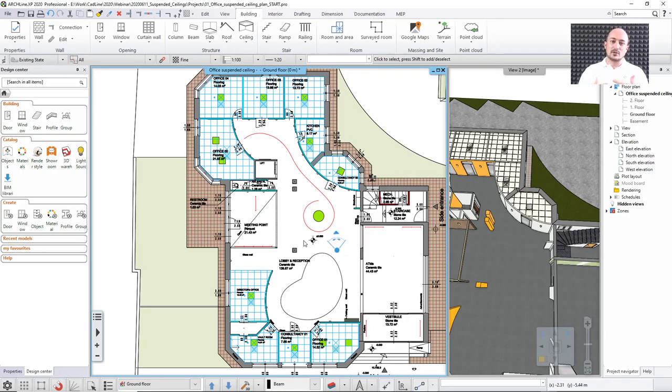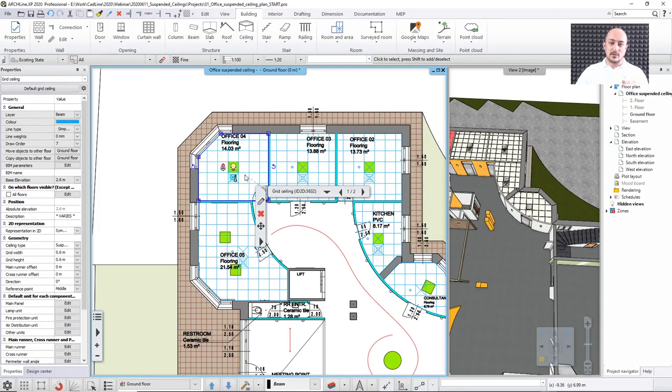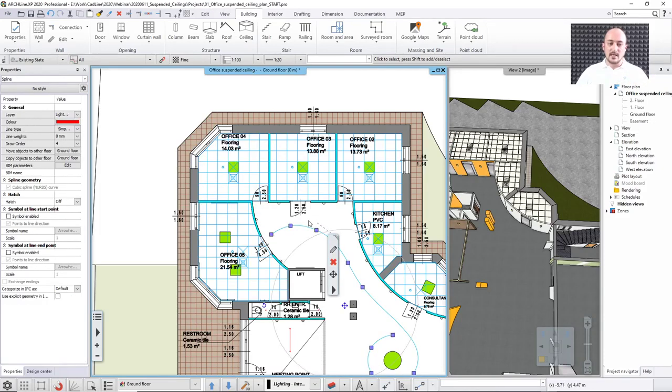So it is faster to generalize it, to create these items automatically and then customize them, than to start each and every time over and over again with the basic settings. Okay, let's just see here. As you can see, this ceiling actually has 3 units in it. When you select the ceiling, you can see the unit symbols. One is a lamp, another is a ventilation system, and the other is for the fire protection system. That is like an alarm attached to the bottom of the ceiling, and by default the software will generate these if you go with the proper settings.